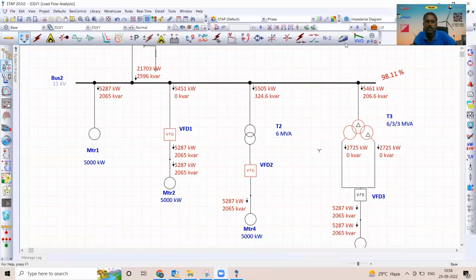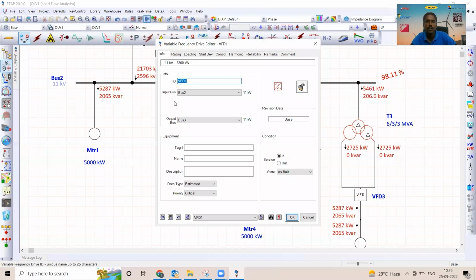See the screen. When your motor is running predominantly at more than 90% of the load at all times, then going for a variable frequency drive is meaningless. But assume that sometimes the load needs only less power, or the power demand of the load keeps changing, then there is always an advantage in going for the variable frequency drive.